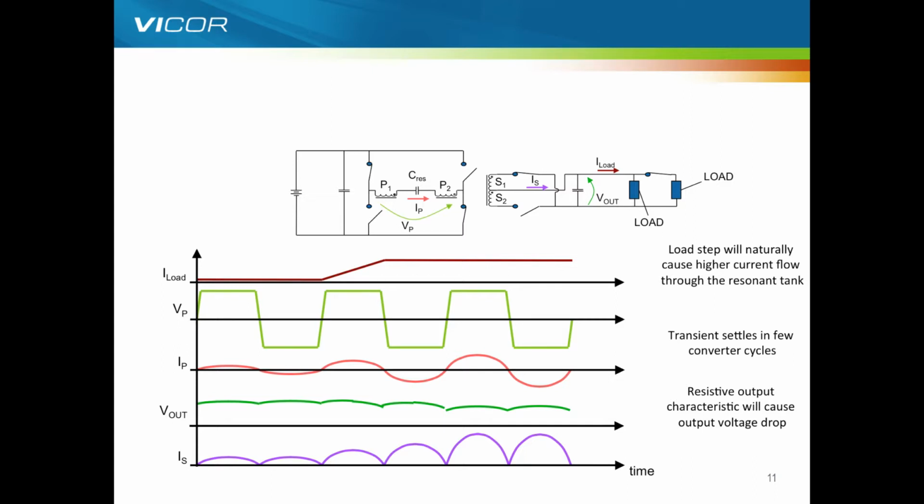You'll also notice that there's a very small drop in the output voltage, which is a feature from the R out, or the natural impedance of this transformer. We'll go on to use that in some of the features later.